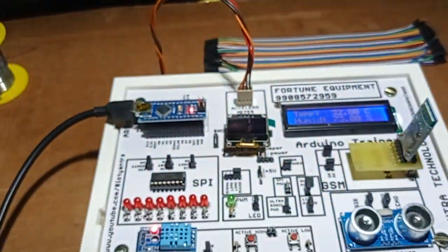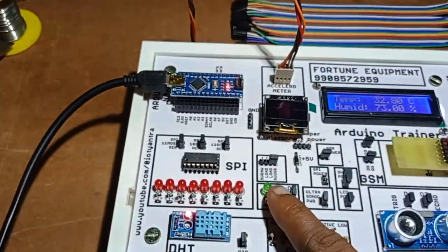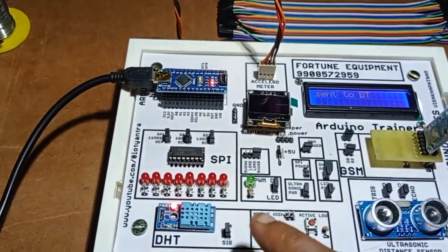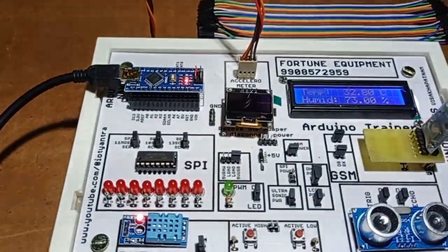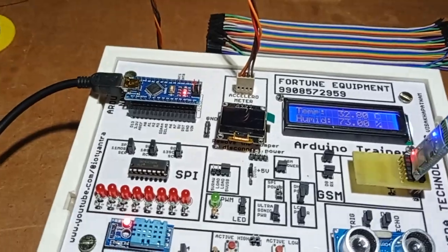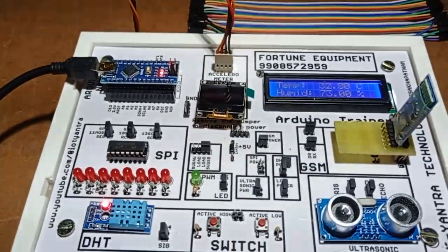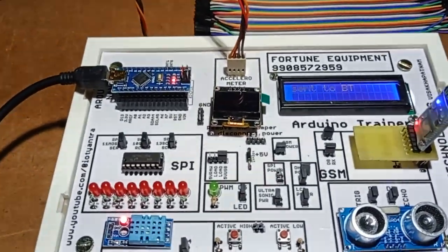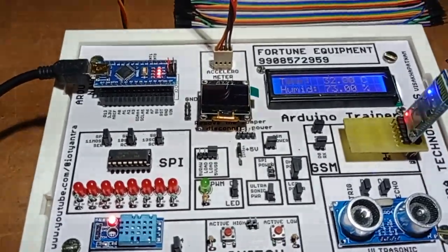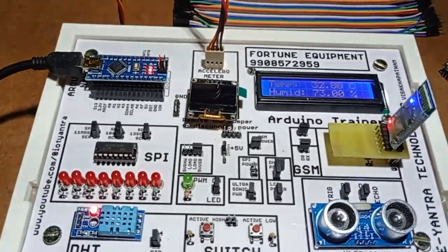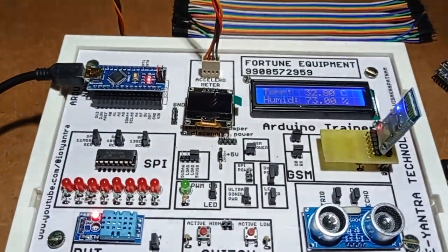What it does is, using a timer, we are going to toggle this particular LED every 1 second. Well, one may ask, what is the fun in doing this? You may use a delay function also, but the problem with the delay function is, if you use delay, you cannot do anything else during the delay time. I mean, the processor gets stuck during that time. So interrupts are really useful to save the processor's power.